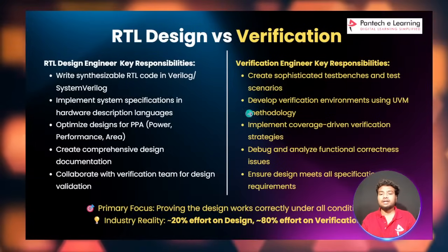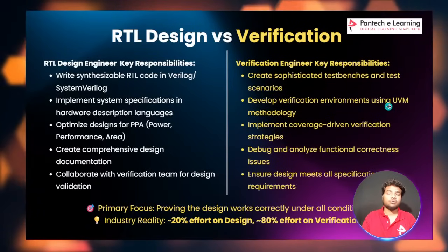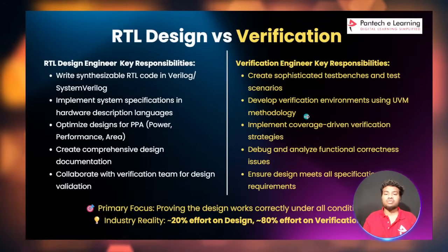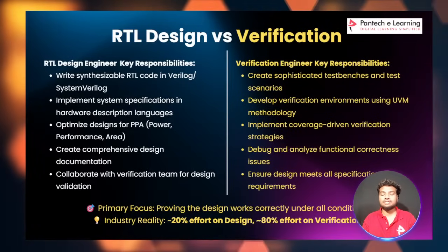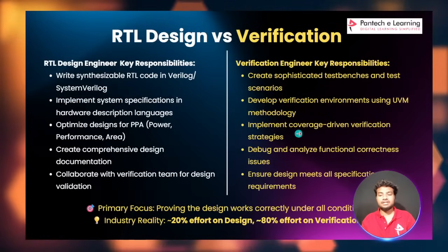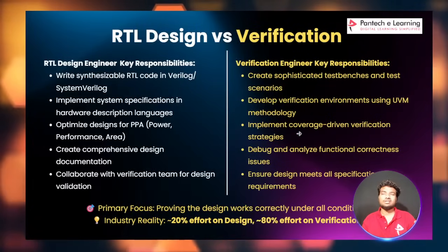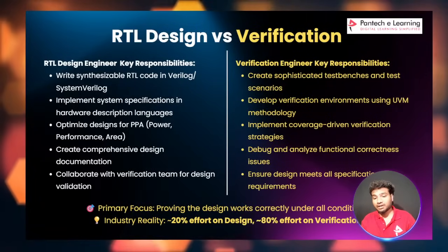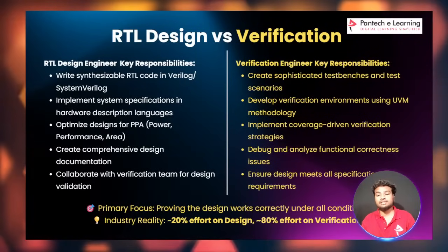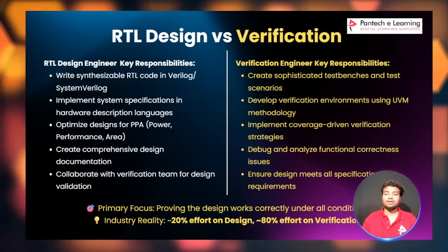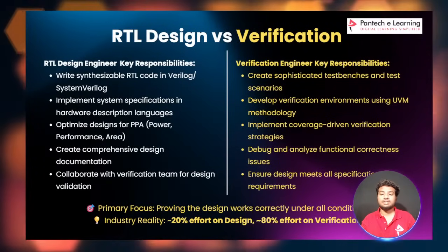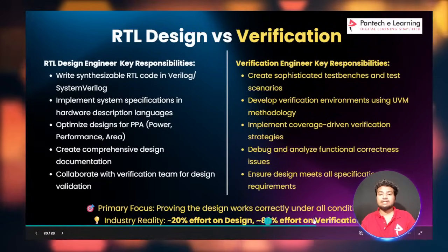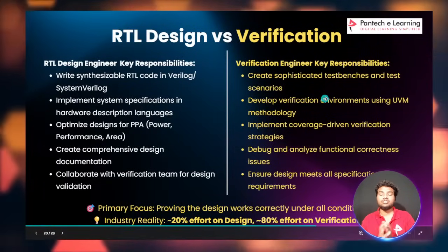Okay, and then develop a verification environment using UVM methodology. UVM is a framework; I will explain what UVM is in upcoming classes. And then implement coverage driven verification. These are some important topics in SystemVerilog: coverage, assertion, constraints. I will tell you one by one in my upcoming classes. And then debug and analyze functional correctness issues. These all come under the verification engineer's part.